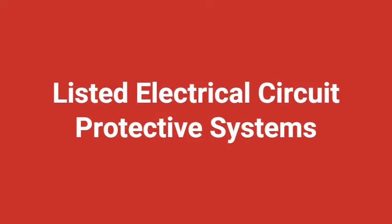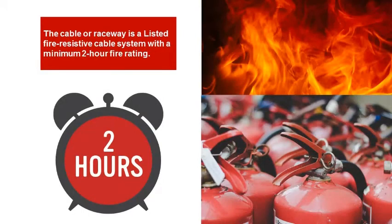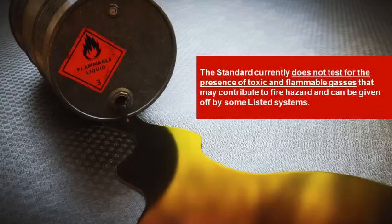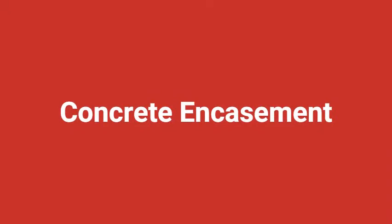Regarding the listed electrical circuit protective systems, what does this look like? The cable or raceway is a listed fire-resistant cable system with a minimum 2-hour rating. This standard currently does not test for the presence of toxic and flammable gases that may contribute to fire hazards and can be given off by some listed systems. Apart from the hose stream test, the standard does not specifically test for mechanical strength during and post-exposure to fire for all listed systems. Full mechanical strength may be needed should building debris fall and impact cables in a real-life fire situation.